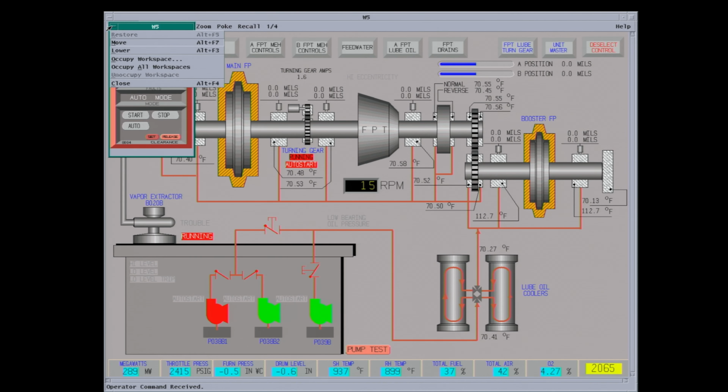This oil temperature is about 70 degrees, which is fine. Too cold, the turbine oil is worse than too hot oil. Gets down to 50 degrees, you can get a lot of oil whip in the bearings. When you shut a turbine down, you want to keep the lube oil on until the shaft temperature cools down below where you'll damage the babbitt and the bearings.